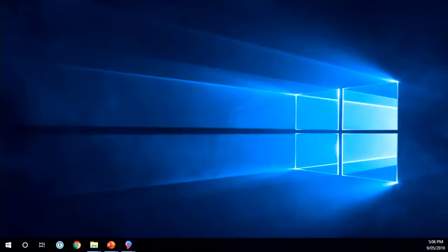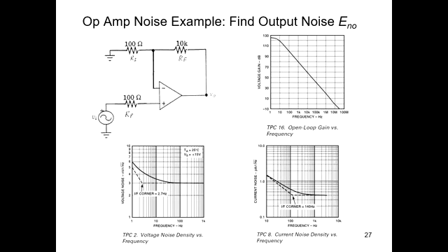That one? It was with the 3 graphs. You're talking about bandwidth of the signal. My reasoning is, what gives you the frequency response here, voltage gain versus the frequency. So I said the half power point is max gain divided by root 2, which is basically max gain times 0.707.